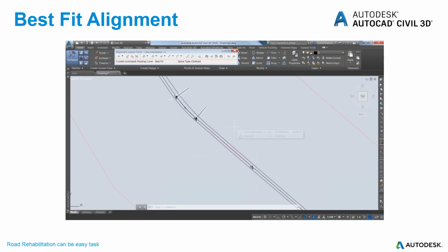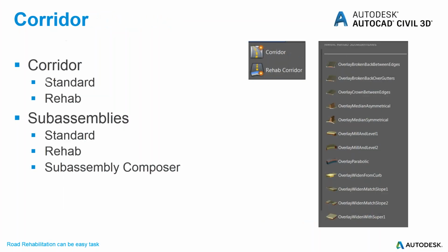Or as I mentioned, if you have a polyline, we can convert it and the system will make a spline line, if you are fine with it, if you don't need some parameters. And in a very similar way we can do it for profile. But now let's move to the corridor. If you have alignment and profile, you can go to the corridor.